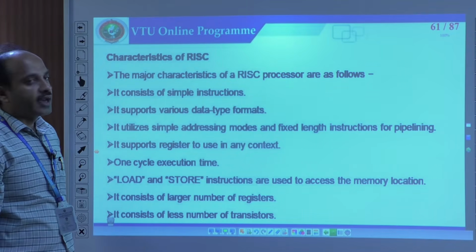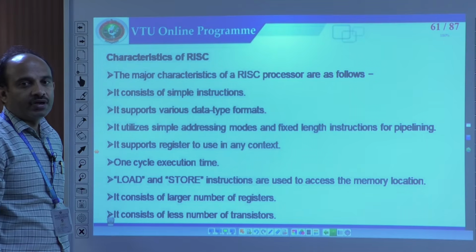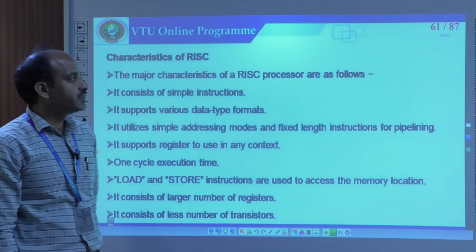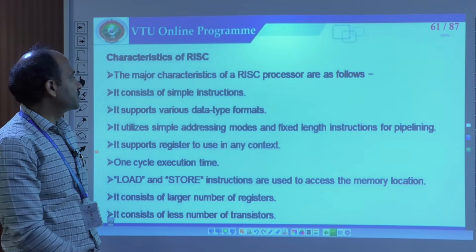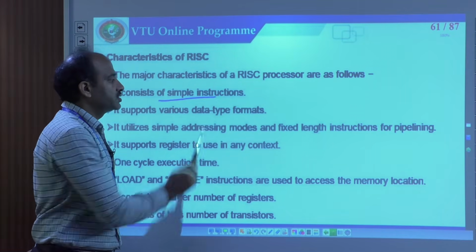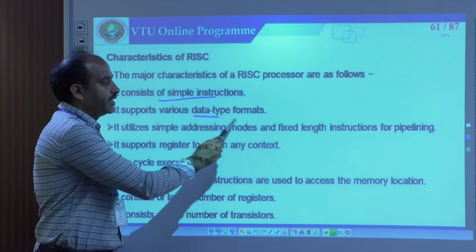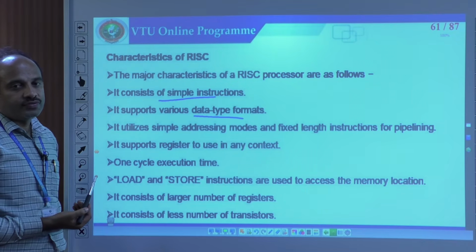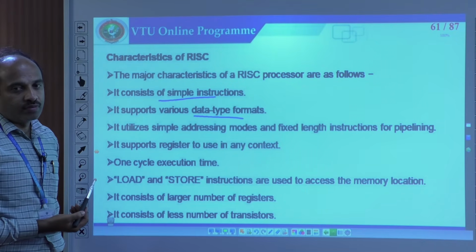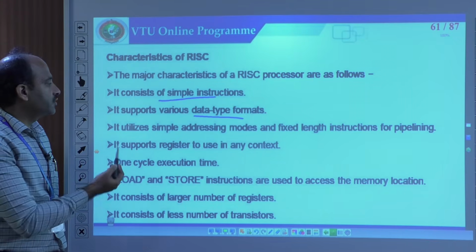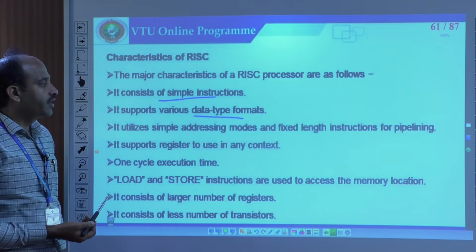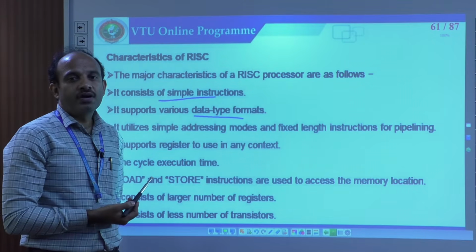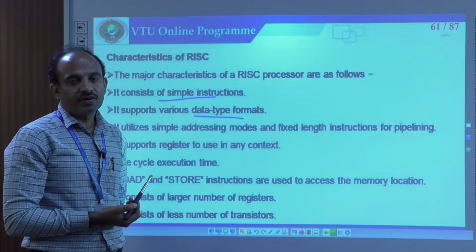And now we will try to understand the different characteristics of RISC. The major characteristics of this reduced instruction set computer are as follows. It consists of simple instructions and a variety of data types, because we have already discussed in the microprocessor that a microprocessor itself supports many different types of data formats, right. Obviously RISC also supports various data type formats, and it also utilizes simple addressing modes and fixed length instructions.